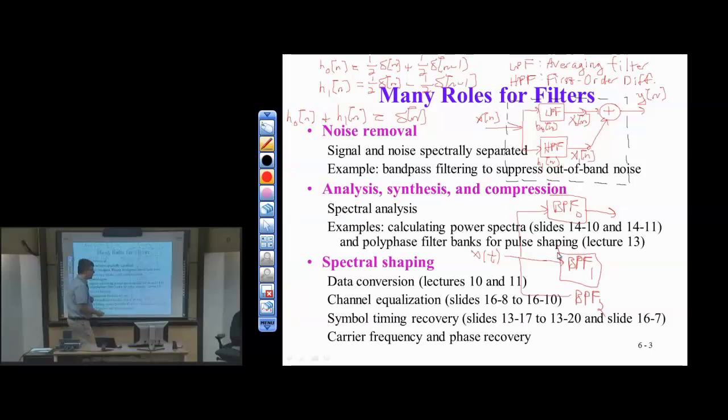And now what I'd like to have is the first bandpass filter pass frequencies from 20 to 200 hertz. This would be the very lowest frequencies in the normal audible range. Take the next bandpass filter and let that have from 200 to 2,000 hertz. And the last one would be 2,000 to 20,000. So the last bandpass filter number 2 would cover frequencies at the high end of the audible range for normal hearing.